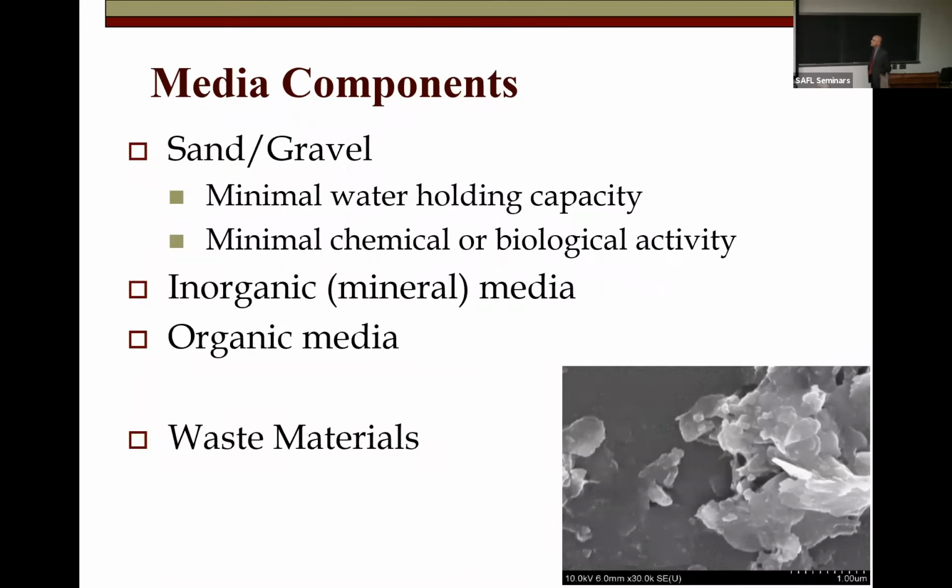Delving into the media a little bit, we can have sand and gravel. A lot of this is related to maybe some structural characteristics or some filtration characteristics. They're not going to hold a lot of water. The sand and gravel themselves are not going to have a lot of chemical or biological activity, although some biomass may grow later on. We'll discuss a little bit about inorganic, mineral type media, and then organic media. As well, there's been a lot of interest in using waste products, and we've done some of that, and some others around have used waste products as well.